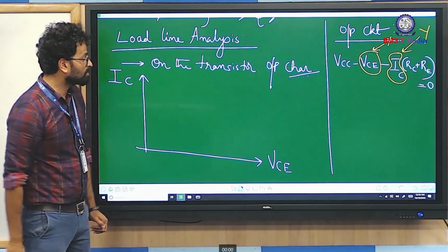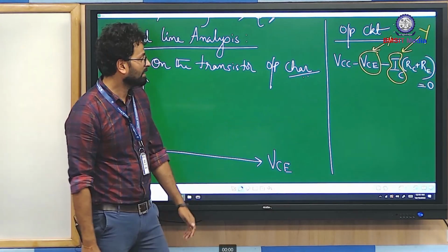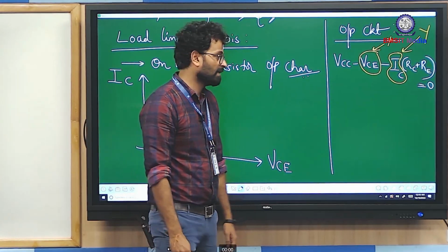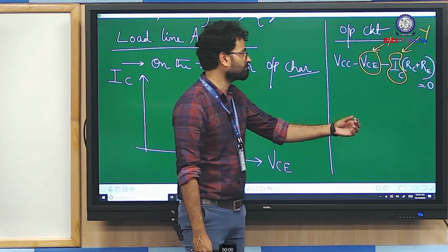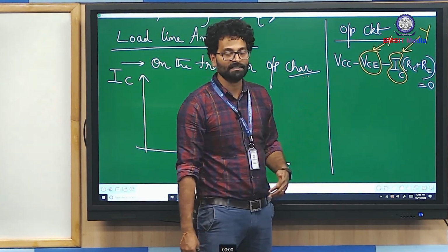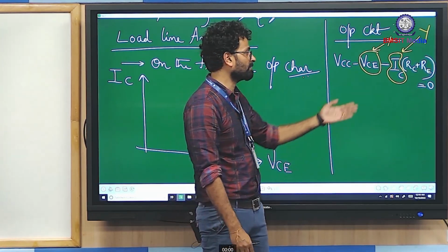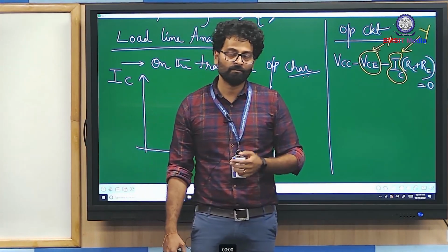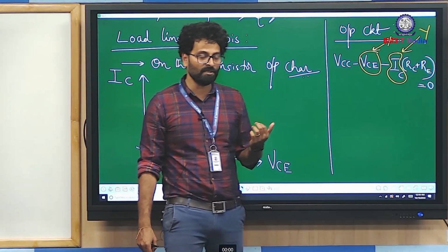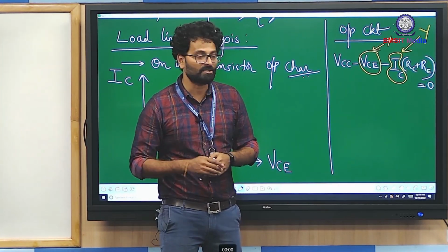In order to draw the load line, you need to consider the x-intercept, or extreme x point, and the y-intercept, or extreme y point. In classical math, we substitute x value as 0 and find the y value. For the second iteration, we substitute y value as 0 and find the x value. But in electrical terms, 0 is attributed to short circuit and open circuit situations.